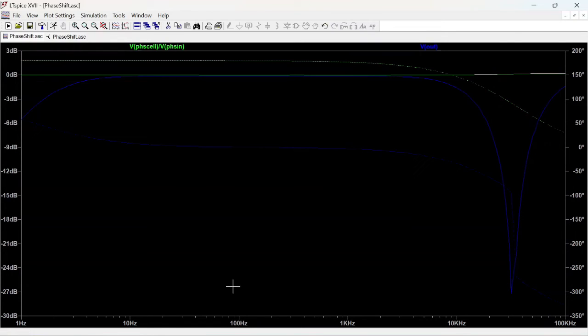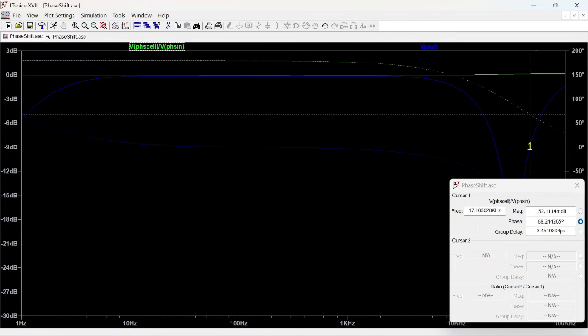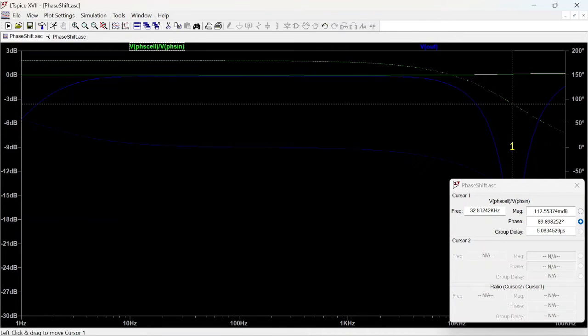So our sweep of this notch would go from 300 something to 32 kilohertz. So I hope that gives you an idea how that JFET works. If we vary that resistance from the highest resistance of the JFET when it's nearly turned off, all the way to when it's completely on, this is that sweep that can happen.